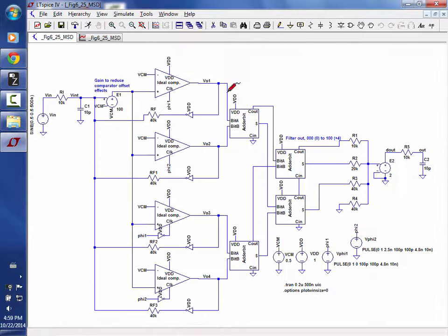Let me ask a simpler question. Is this a filter of (1 minus z to the minus 4) over (1 minus z to the minus 1), an averaging filter of 4? Why or why not? Okay, so I've got the bits coming out here, and I'm adding, let's say, bit 1, bit 2, bit 3, bit 4, bit 5, bit 6, bit 7, bit 8, bit 9. I'm constantly adding the bits up. Tell me what you think of this.